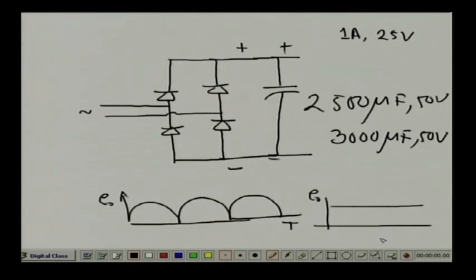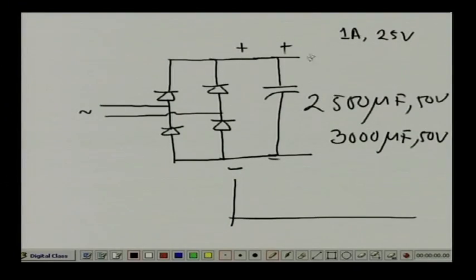Now, the problem arises, you see that when you switch on, now what will happen here? Now my output voltage, suppose this is the output voltage, right. Output voltage will look like a slight fall, then again it will rise like this one, right, fall, because before the capacitor fully charges, again it will fall like this one. With charging and discharging of the capacitor, it will look like this one, almost steady DC voltage.